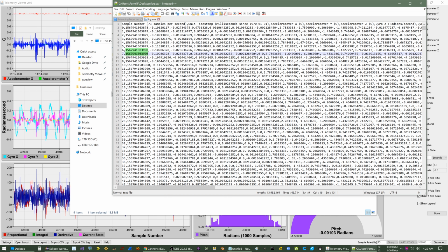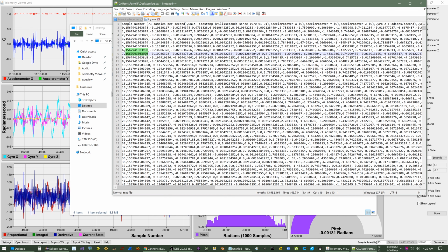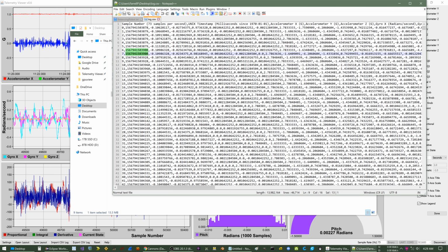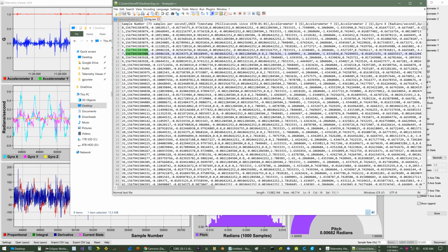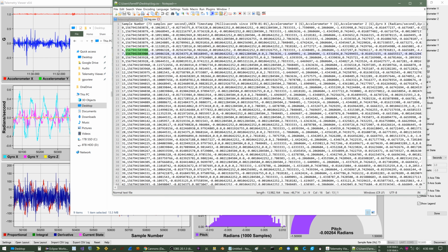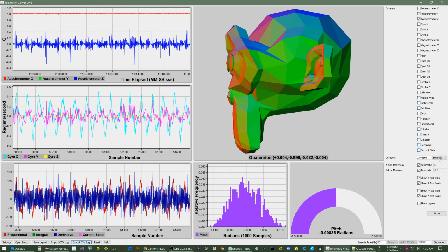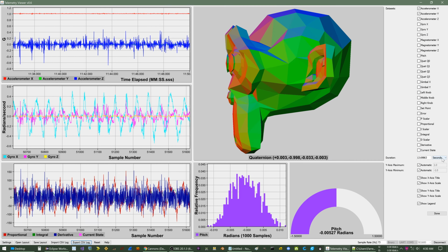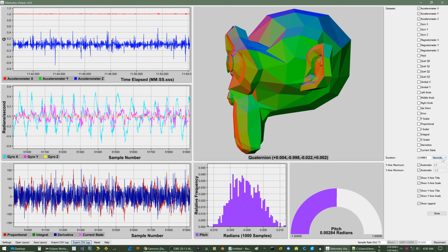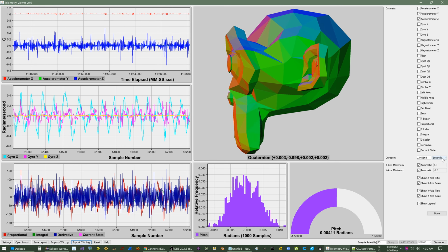One thing to keep in mind is if you're sending telemetry very quickly, like, I don't know, 10,000 packets a second, then the timestamps will clump together because it just depends on whenever the driver processes the data. So I wouldn't recommend using time for the duration if you're sending telemetry very quickly. But it works fine for tens or hundreds of samples per second.